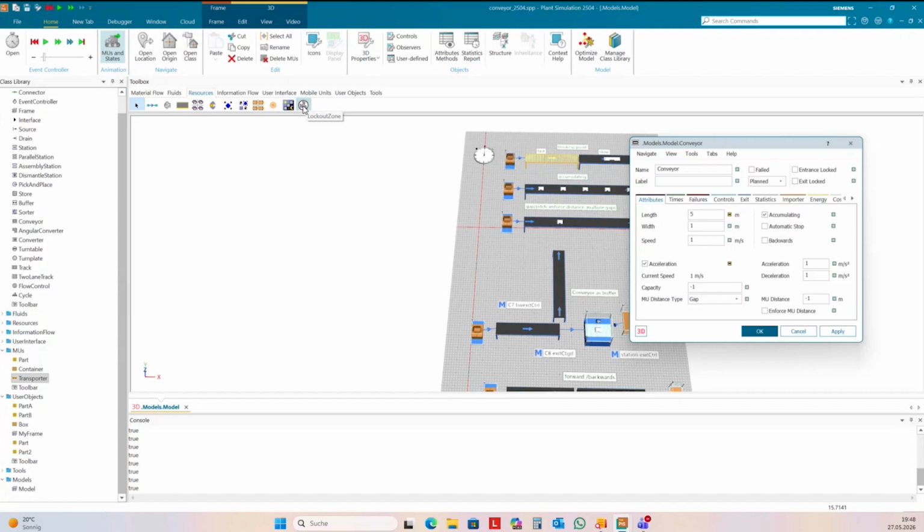Yes, but it's not really time consuming, but not in 5 minutes or 10 minutes. You need an overall control for this. You need to feed the parts into the system, then make your processing, and then move it out, and then you can start the next sequence. So you need an overall control for this. But it's not so difficult. And with the backward movements, you need maybe a control for the conveyor to move the parts if you cannot connect it with connectors. But it's not complicated, no.